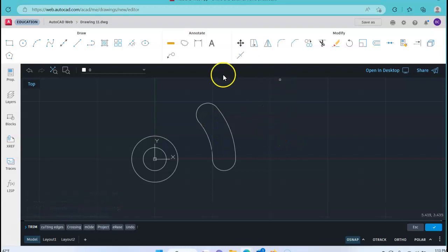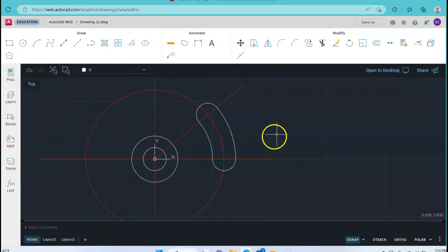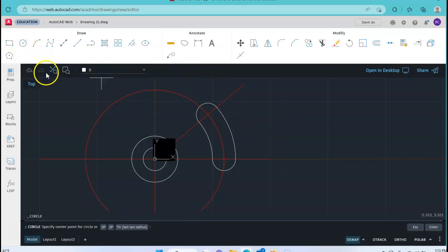So we'll go ahead and get a couple more in here now that I've got this. Let's turn that center line back on. Layer, so center line layers back on. And now I'm going to create a couple more circles from around here to create, there's like a hub around this slot. It's kind of the way I'm interpreting it. We can't really tell that for sure from the way the drawing is. We would need a second view to find out what the actual designer had intended for this part. But for right now, we'll just kind of draw this as the 2D front view.